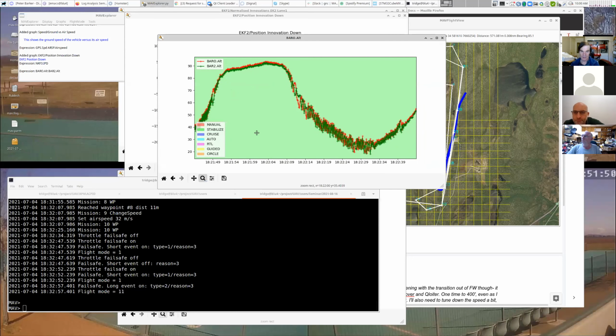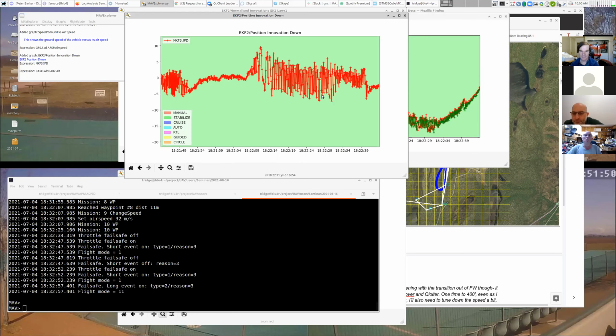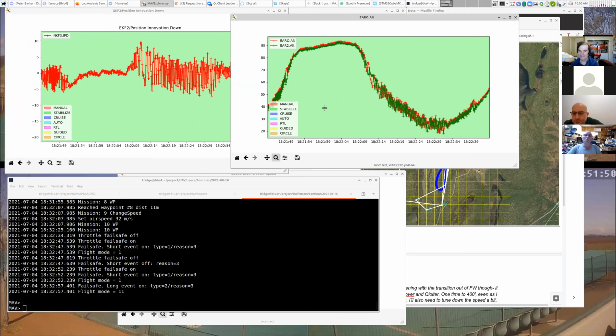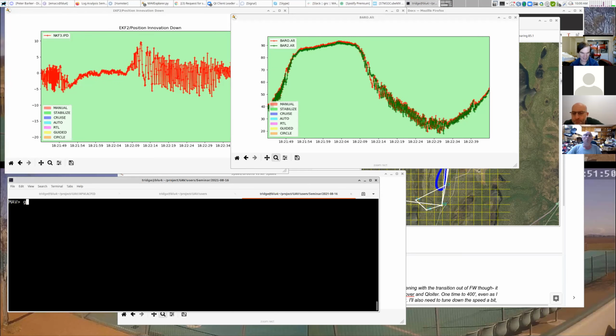With all of the cubes, the barometers inside are measuring the pressure at the USB port. Effectively, that's the biggest hole into the cube. So that's where you're measuring the pressure, at the flow location for the USB and SD access point. If you get airflow past that, that can create turbulence, and you can see some quite noisy measurements. If I've got one exposed to the airflow, I'll put a little bit of tape over that hole if I'm flying it in a copter exposed to airflow. That's a very good suggestion.